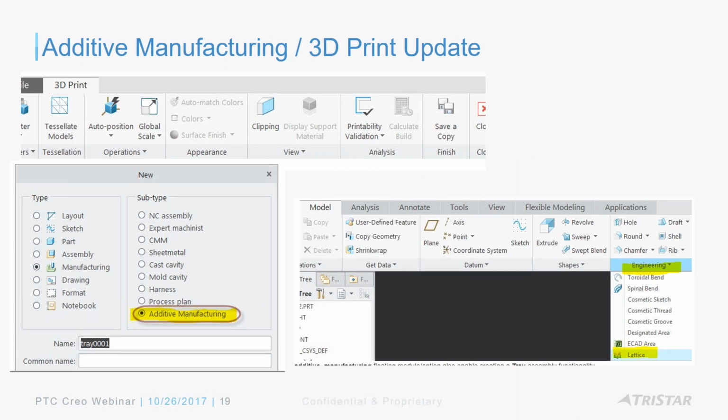Many of you may have heard of additive manufacturing and how industries are adopting it. PTC is trying to bridge the gap between the 3D CAD model and the additive manufacturing world. The first step was in Creo 3, where they introduced 3D print. If you have a Stratasys printer, you can check for printability and place it on the tray, all right from within Creo, instead of exporting an STL and doing that in the printer software.